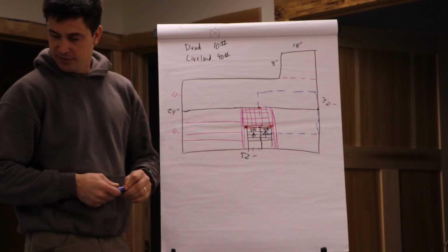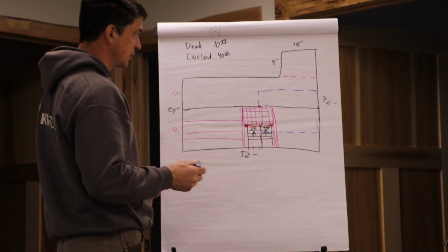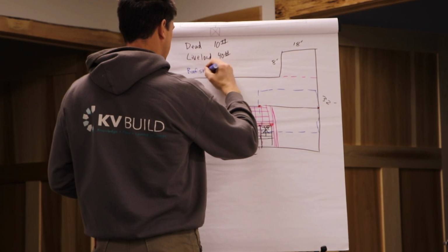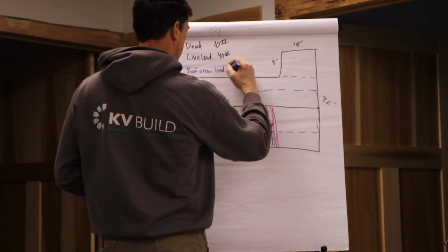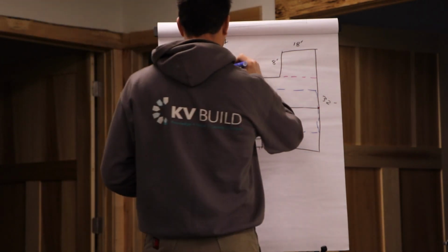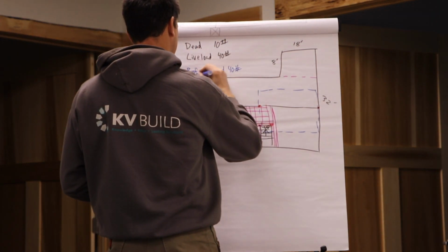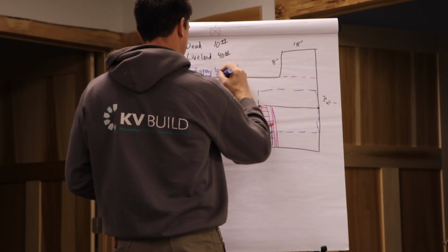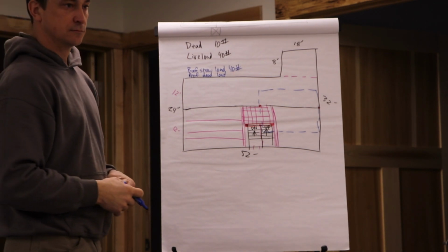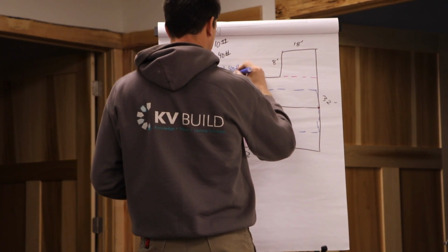How do we know how much load that is? Okay? And what do we have to do? What's our roof snow load? 40, thank you. 40 pounds a square foot. And our roof dead load, what do you think? 15, probably. Okay, 10 to 15, somewhere in there. You could say 20. Let's, for fun of it, say 20 pounds.